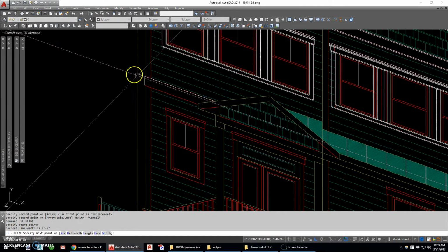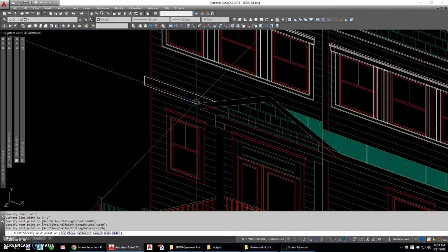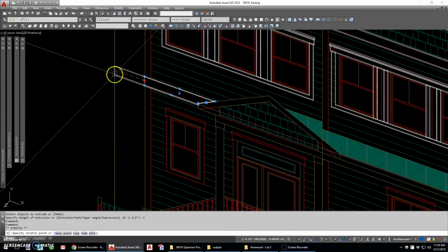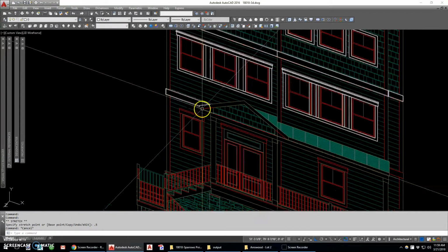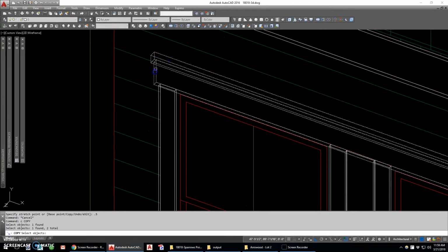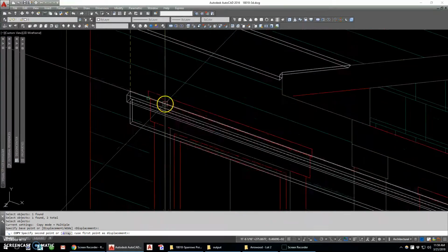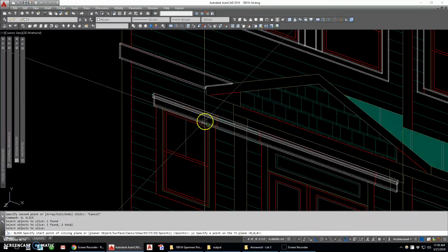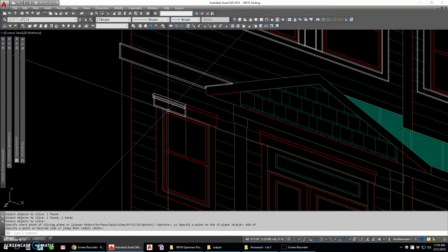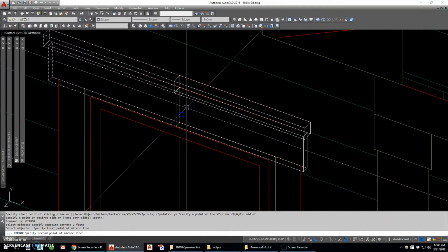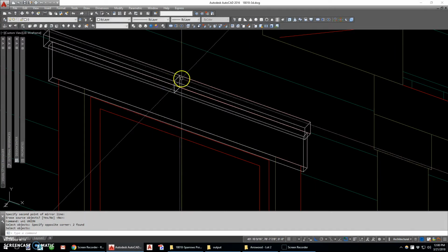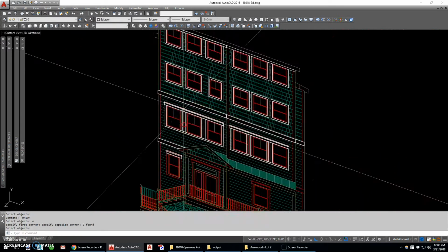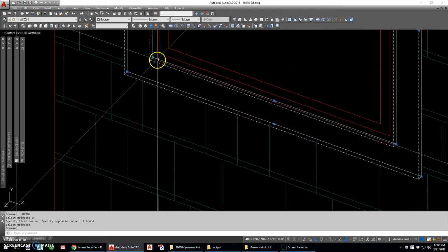So again, I'm going to draw a polyline over this. Close it. Extrude it. 1. Pull this node out another 1/2 inch. I'm going to borrow this header, copy it down to here, slice these things at the middle of the window, keep that side, mirror this over, union this stuff together and this stuff together. I could probably union the whole thing together.